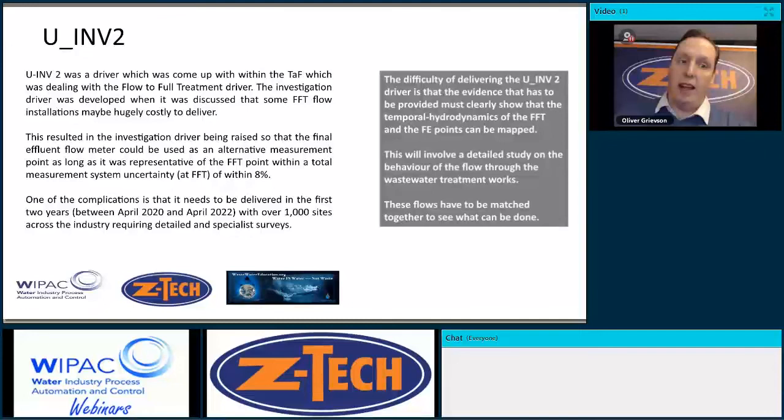And you've got less than something like 200 mil on that particular site to put a flow meter in. Practically, no flow measurement structure could be installed there. Practically, that means you're going to have to take down the whole front end of a wastewater treatment works.